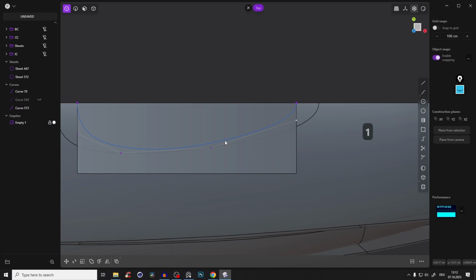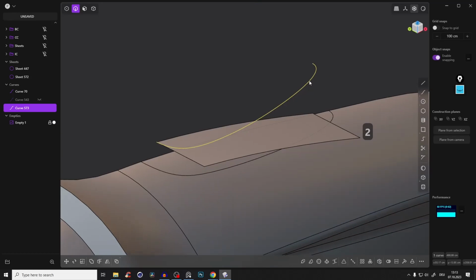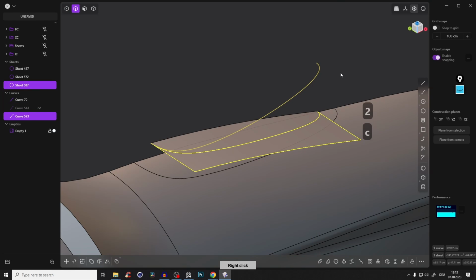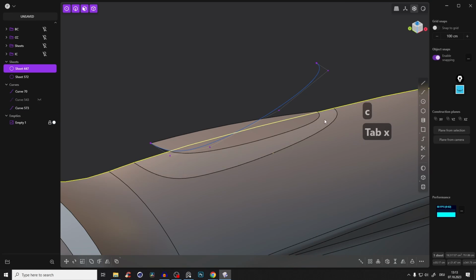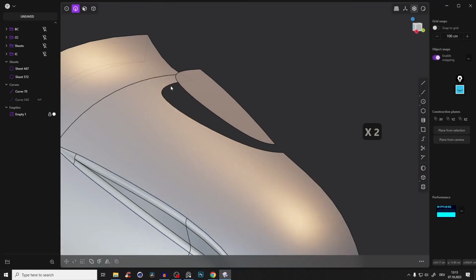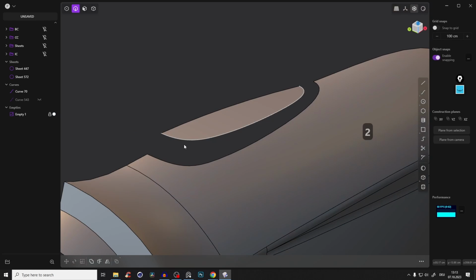And again, let's create a nice button, cool, nice little thing here. The shape is not very important for me right now. And select that curve. This time you can cut into this body sheet. Select this sheet and delete it. And this curve, we cut it, so bring it into CC. Beautiful. So we have basically our button.